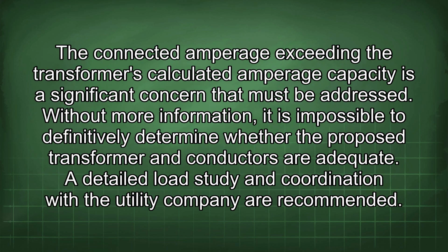The connected amperage exceeding the transformer's calculated amperage capacity is a significant concern that must be addressed. Without more information, it is impossible to definitively determine whether the proposed transformer and conductors are adequate. A detailed load study and coordination with the utility company are recommended.